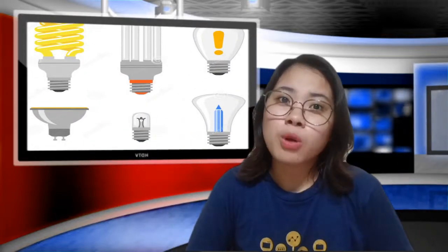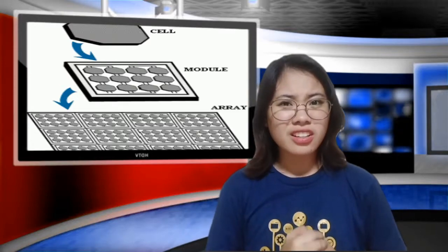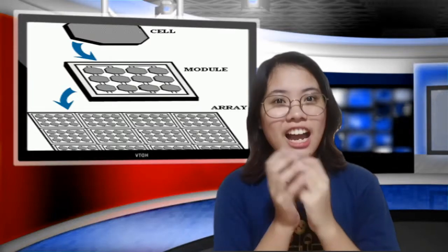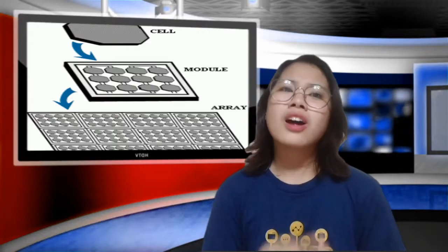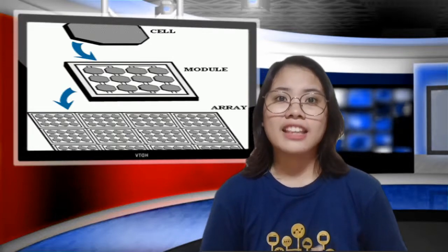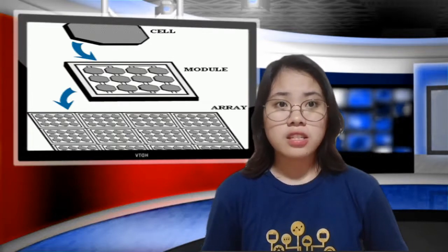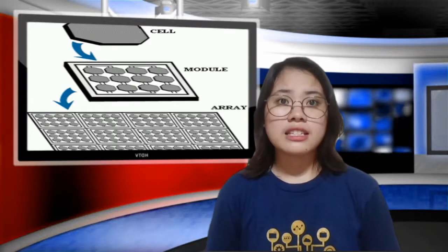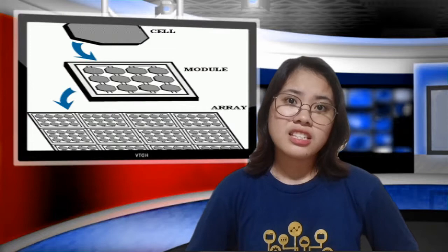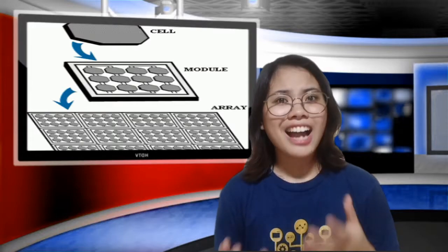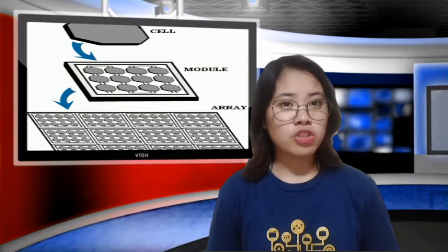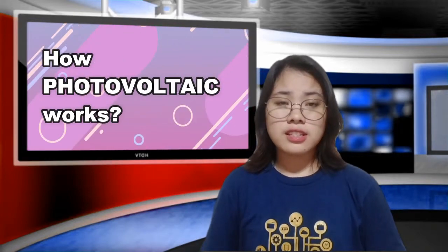A photovoltaic module is a collection of solar cells that are electrically linked and installed on a support structure or frame. The modules are made to provide electricity at a specific voltage, such as 12 volts in most cases. The current generated is directly proportional to the amount of light that strikes the module. An array can be formed by connecting many modules. In general, the greater a module or array's surface area is, the more electricity it produces.